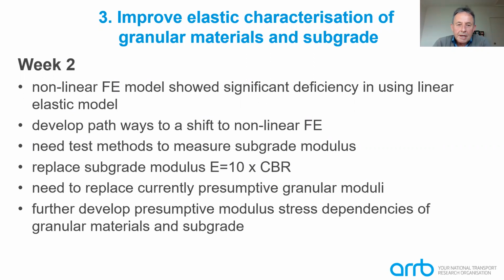Another area that needs some further development is the elastic characterisation of granular materials and subgrades. And I talked a bit about that in week 2. And I gave you some idea of the work that we've been undertaking with non-linear finite element models to improve the ability to predict the modulus of granular materials and subgrade compared with our current linear elastic model.